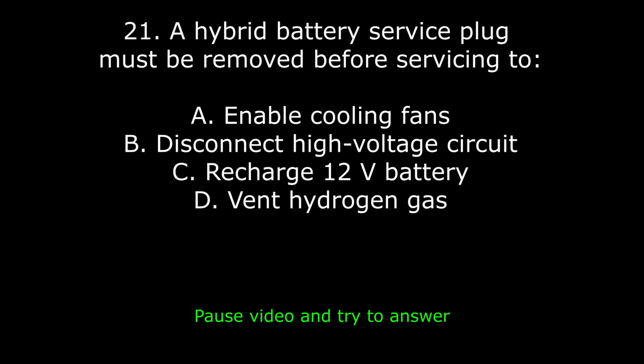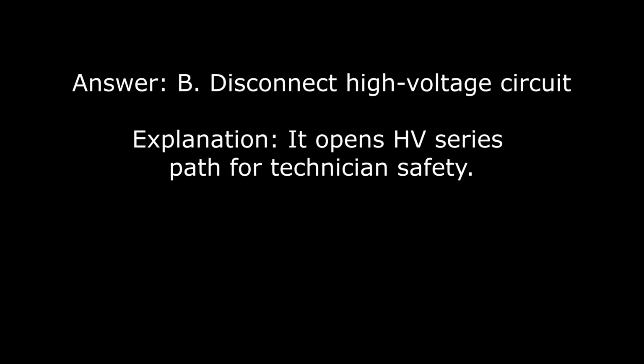21. A hybrid battery service plug must be removed before servicing to A. Enable cooling fans. B. Disconnect high voltage circuit. C. Recharge 12-volt battery. D. Vent hydrogen gas. Answer: B. Disconnect high voltage circuit. Explanation: it opens HV series path for technician safety.